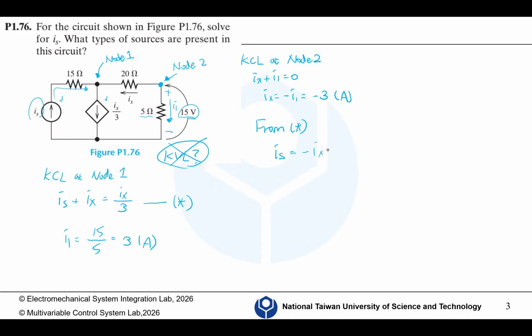In this problem, it's mesh current analysis. We define meshes in this diagram. A mesh is the smallest loop. So we have 3 meshes, and this is 2.14. Okay, we look at mesh 1. We apply KVL at each mesh. For mesh 1, starting from the bottom left corner, I1 is running clockwise.